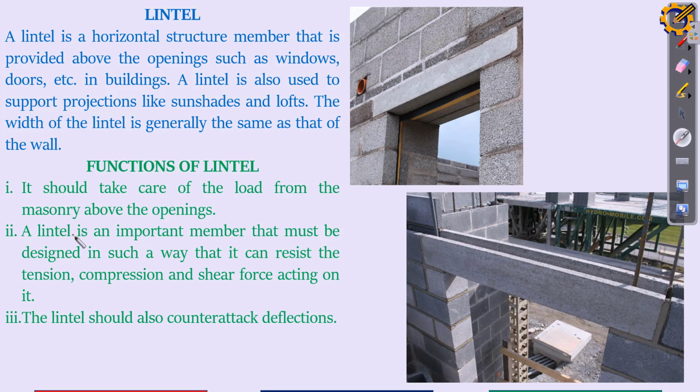Functions of lintel. A lintel is an important member that must be designed in such a way that it can resist the tension, compression, and shear force acting on it. On top of this lintel, you have walls, you have everything. Imagine there is no reinforcement inside this thing, it would collapse because there is a load acting on this area. So it is the lintel that is supporting those loads from tearing off into the wall opening. The lintel should also counter deflections. So that's one of its primary purposes.